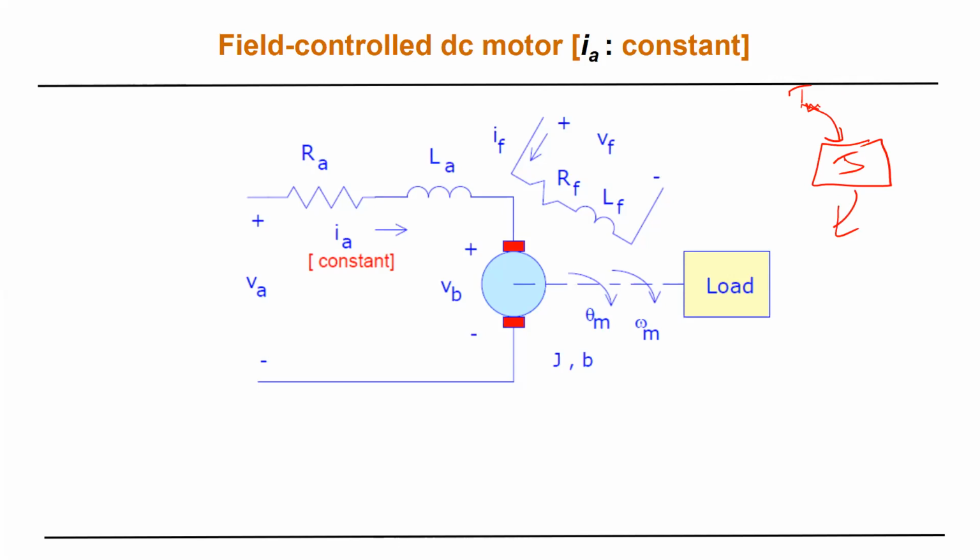So it will move it in one direction. What are the other torques in here? Which torque will be? The friction. And what is the direction of the friction? Opposite, which is basically B omega. So if you apply Newton's law in here, I have Tm or TL, let me call it TL to be on the safe side, minus B omega.